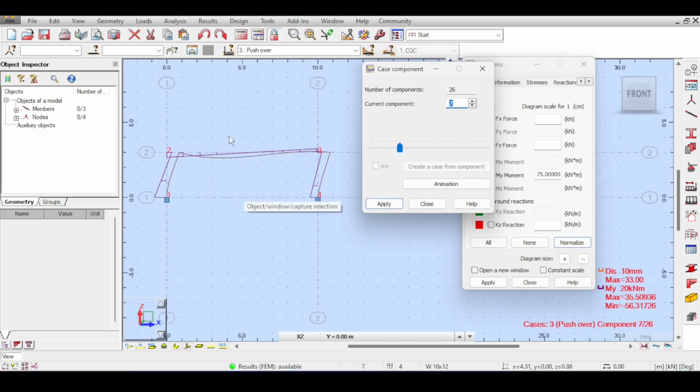Of course, for structures, you should apply a hinge at the edges of the beam or any member and at the center of any member. Now, this is why I told you Robot doesn't have a quick material nonlinear model, because this is only an approximation. Because we know for a fact that the maximum moments happen at those hinges, we are able to apply some internal hinges there.